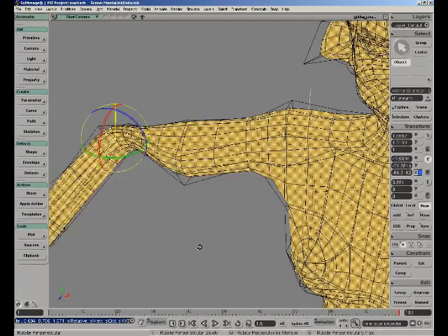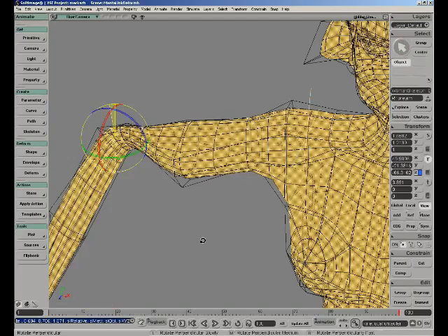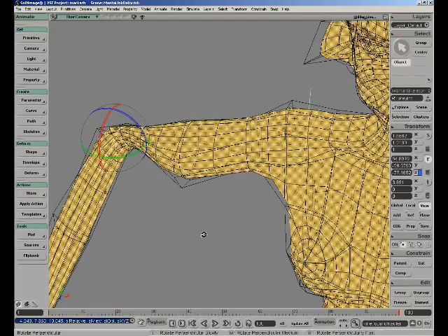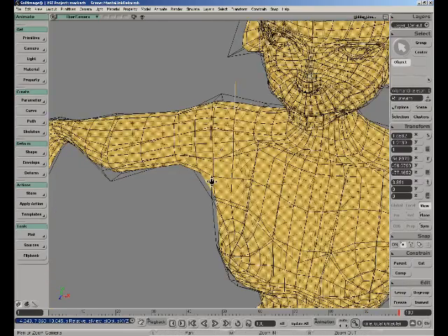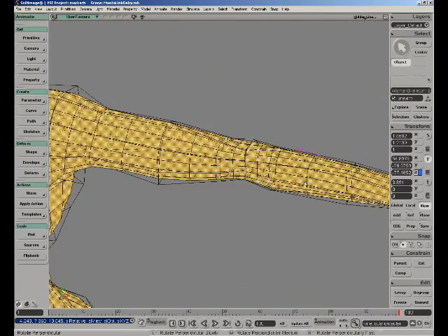With the new Link Deform tool, we're able to very easily link an object's shape deformation to any other object's orientation or any animatable parameter on that object. So here what you can see I've done is link the orientation of this bone to the shape deformation on this muscle. So to set that up on this side of the character, it's very simple to do.